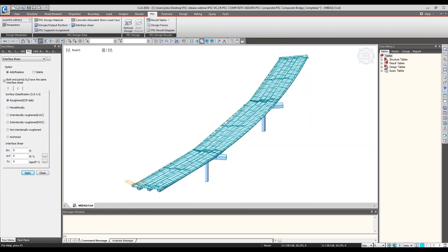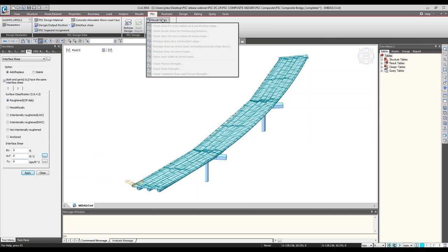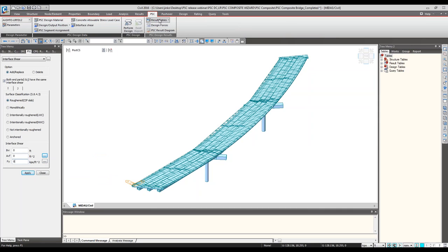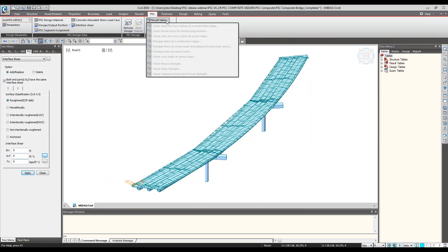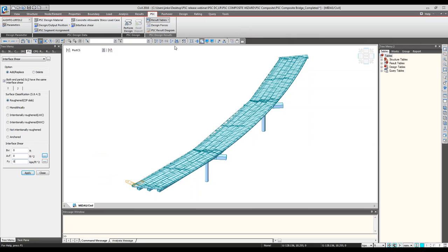And for shear reinforcements, the user needs to manually select the diameters, the number of the reinforcements and spacing, and the strength for the reinforcement. Performing design and checking the result table will provide you a result table very similar to the one that I presented in the PPT.